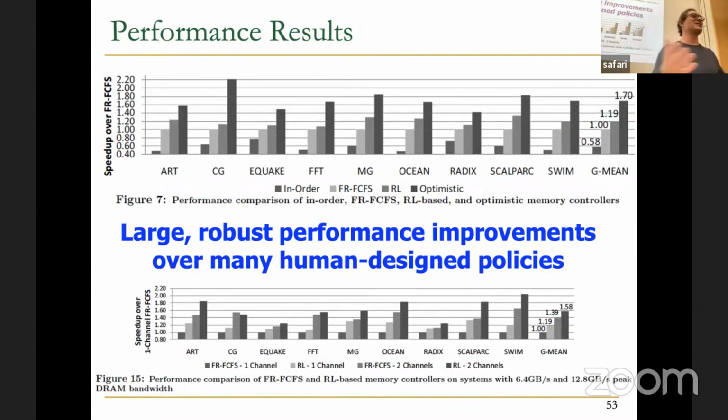When we talk about simulation, we'll talk about simulators that used to have such no bandwidth constraints, and as a result, they modeled memory in terrible ways. But essentially, if you have only the data bus constraint, but no other timing constraint, you get about 70% performance benefit. So we're getting 19% of it, which is not bad. And this is a pretty aggressive upper bound, 70%. And I should also say that the numbers may look low because these are applications that we could simulate at the time. Today's applications are much more intensive, and we could have done maybe even more intensive simulations.